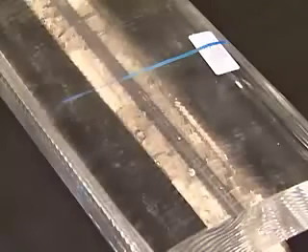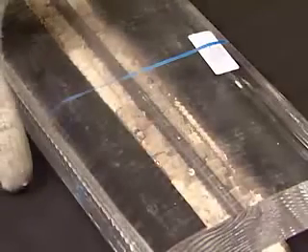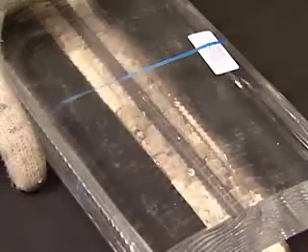A variety of grinding machines and pressing machines are used depending upon the type of lens. Based on lens diameter, shape, and specific gravity, the necessary volume of glass weight is precisely calculated, and after cutting with a diamond cutter, is adjusted by units of 1/10 of a gram. Large aperture lenses used for EF 500mm F4L IS USM are cut by hand using heat.